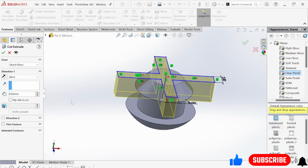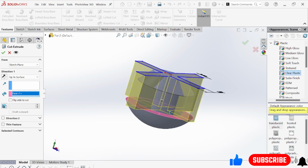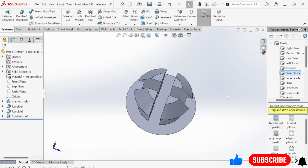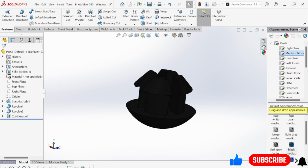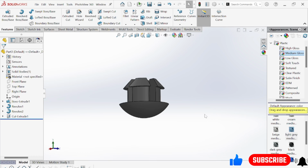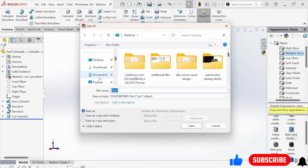Go to extrude cut. Select up to surface and select this surface. Now here you see this is the part that we need. Actually, it's the plastic part. So go again to plastic, go to medium gloss, select black medium. Okay, select this gray medium. You can select any part. This part is fine, and save this one. Let me save this on the desktop and name it connector.